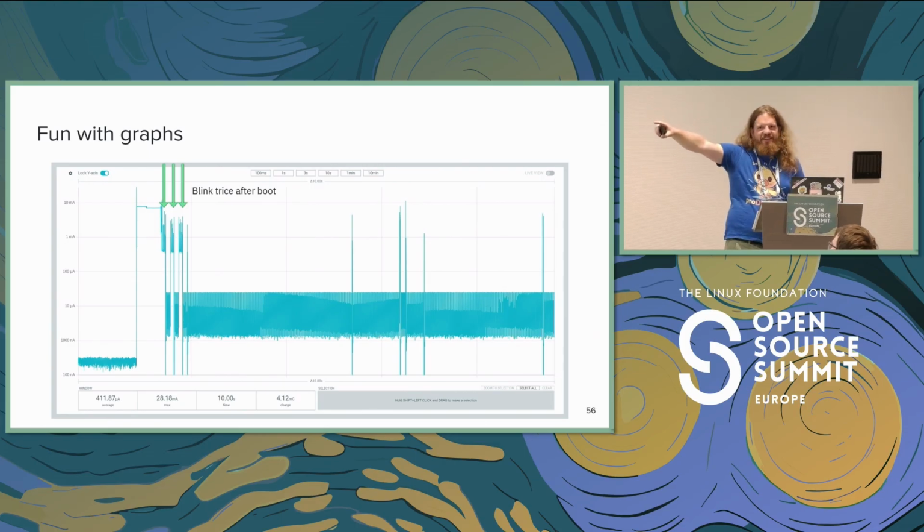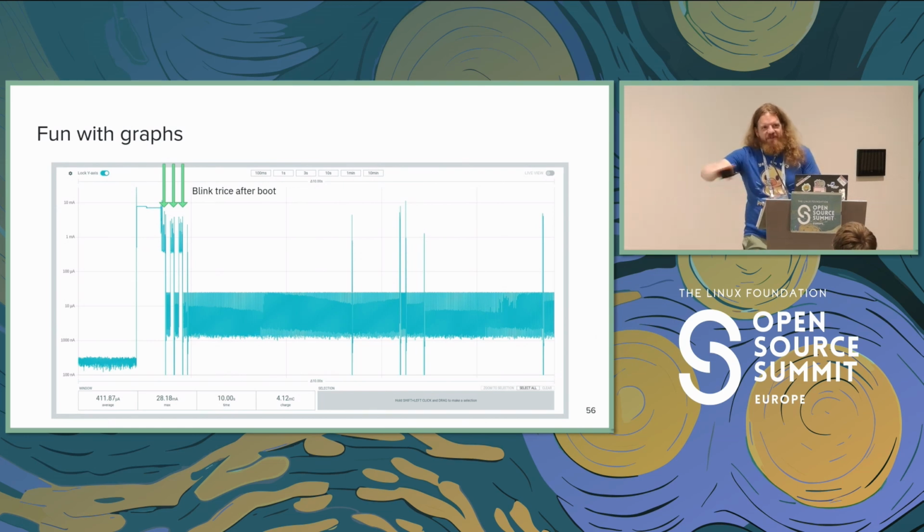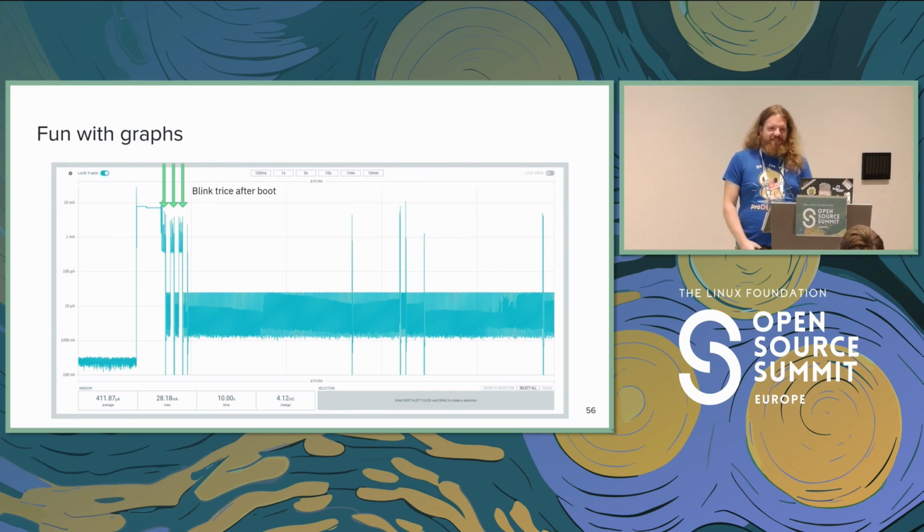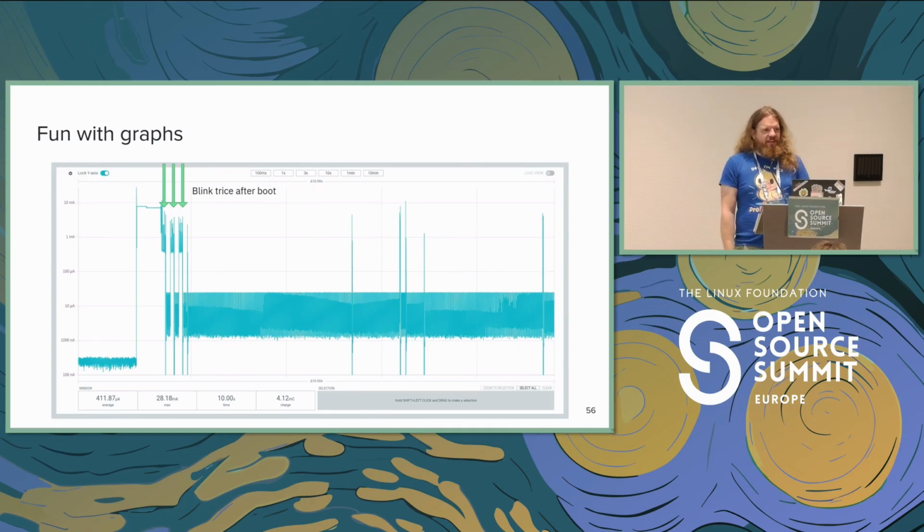So if I did a shutdown to get some more juice out of it, the low power states wouldn't make up for the initialization sequence. Shutting down this device would make sense if the next 6 months I'm not going to do anything. But if I'm just going to idle here and have a Bluetooth advertisement every minute, don't do shutdown. And like I said, for standby there's currently no support in Zephyr.